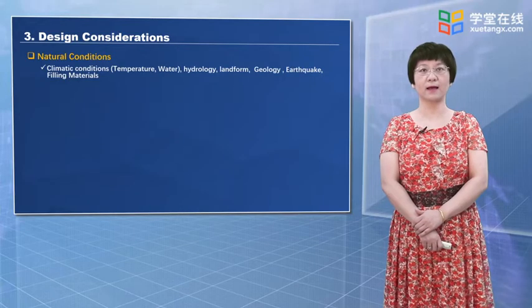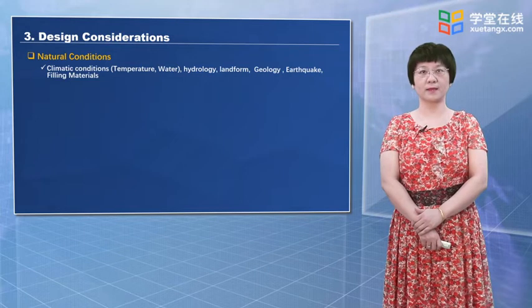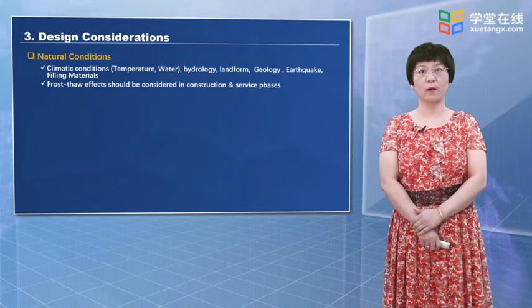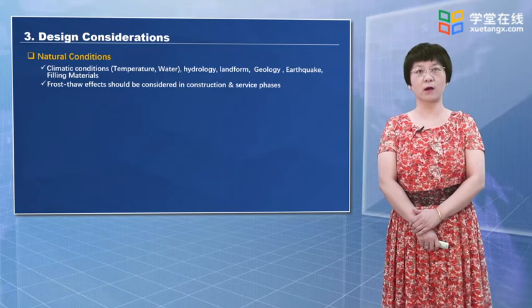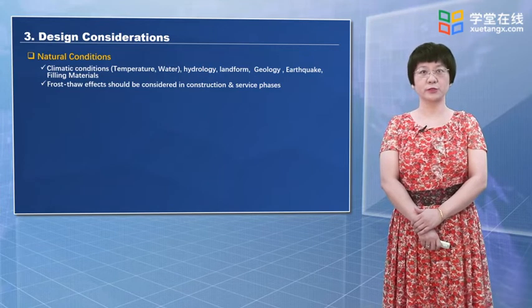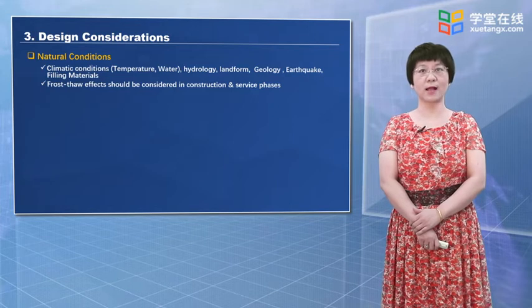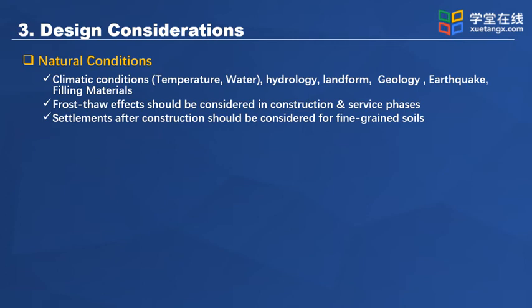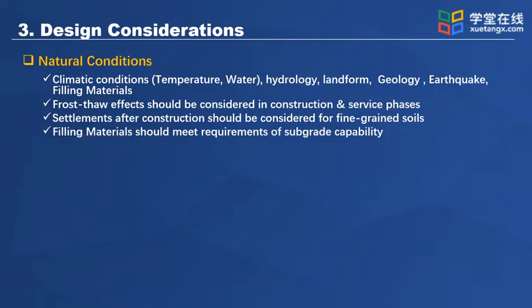The climatic conditions mainly mean the temperature and water. The combination of water and temperature will cause frost heave and soil settlement, which should be considered in construction and survival phases. Settlements after construction should be considered for fine-grained soils. Fill materials should meet requirements of subgrade capability.